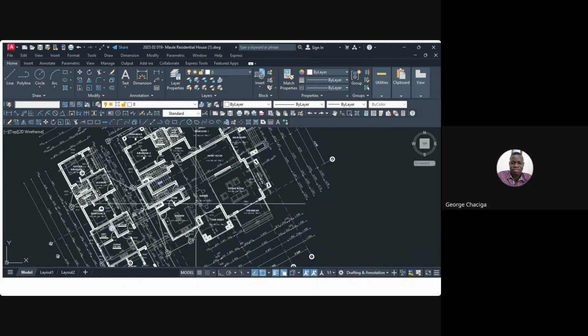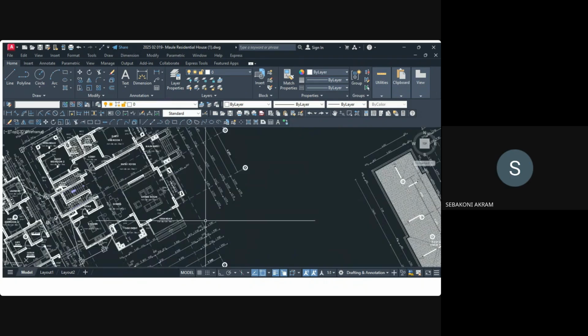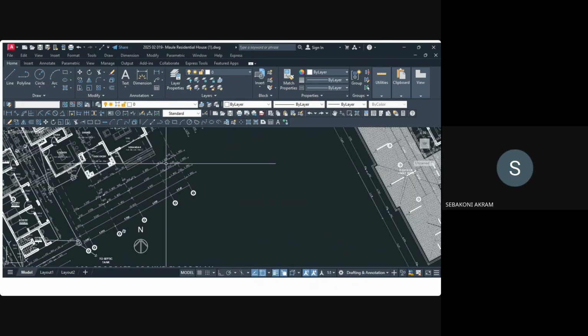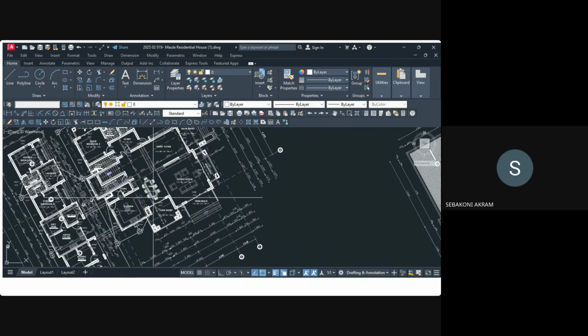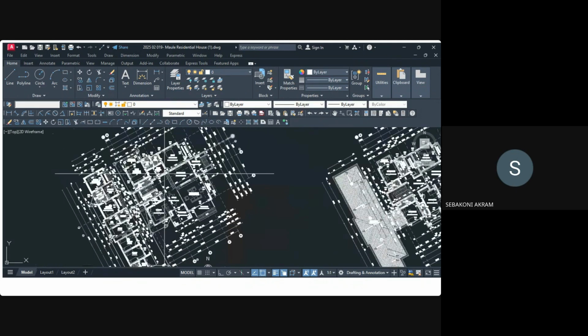But before starting, before doing all this analysis of the drawing, first of all, in MEP design we don't need much of these dimensions of the wall. There is a lot of detailing in this drawing that you're seeing that really needs to be cleaned off. So the most important bit of starting the electrical drawings is the cleaning process, and you have to do it carefully, leaving all the necessary details and deleting all the unnecessary details.